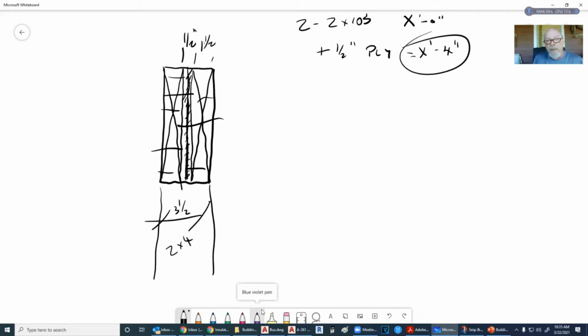So when we talk about lengthening these, this is now steel. You can use a flitch beam, which is just a 1/2 inch piece of steel, and it adds many feet to the span. However, we have the problem of heat transfer through conduction massively, because everything's touching all the way through here.